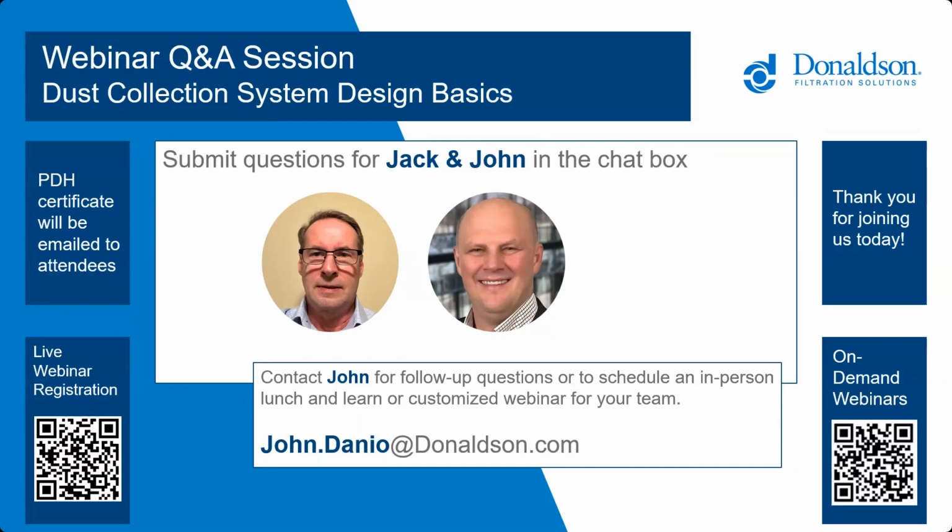All right, thank you. Do you typically recommend, or are there any pros and cons of putting a collector inside versus putting a collector outside? If you can put it inside and there's no regulatory issues or concerns, that would be the way to go. The advantage is that your temperature doesn't change, which is helpful. If you take it outside, depending on where you're located, you're going to go through some dew points possibly if you're not running 24/7. So that is a concern.